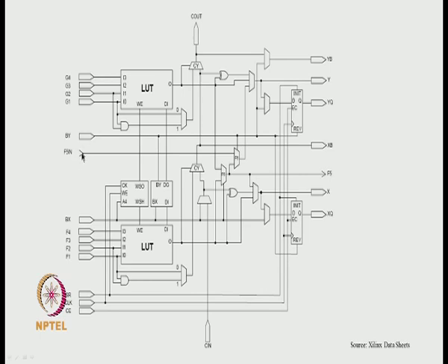And now you can see that, assume that the F5 output is coming here. In the case of a single CLB, this F5 output is connected to the F5 input of the next slice. So that is coming here, and you see this F5 output and the F5 output of the previous slice are combined in an F6 mux. The select line of that, the BY, can be used for the 6th variable. And that F6 mux can be directly taken out or can be registered in this particular flip flop.